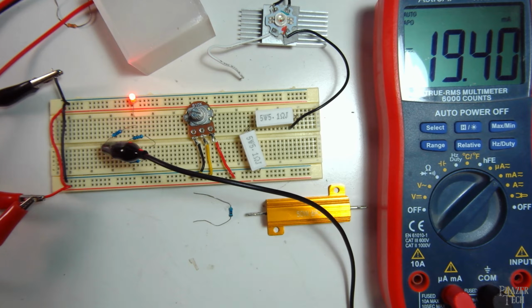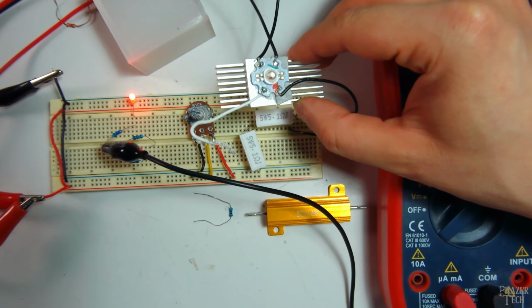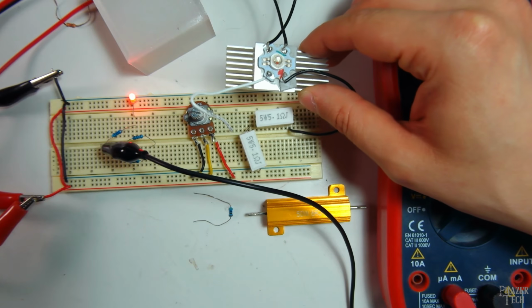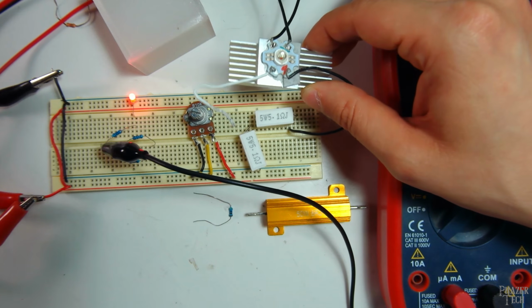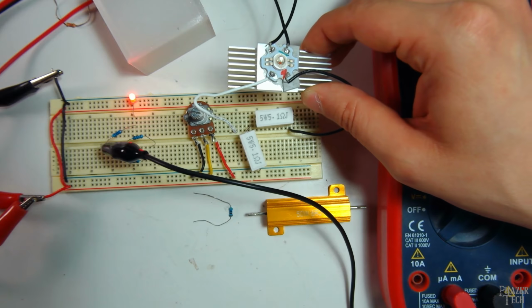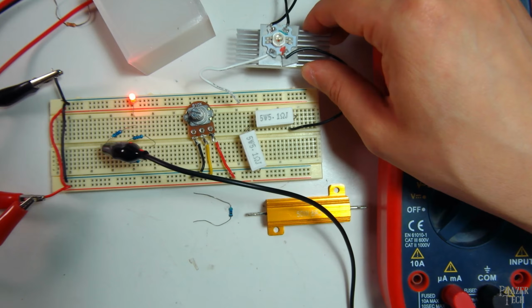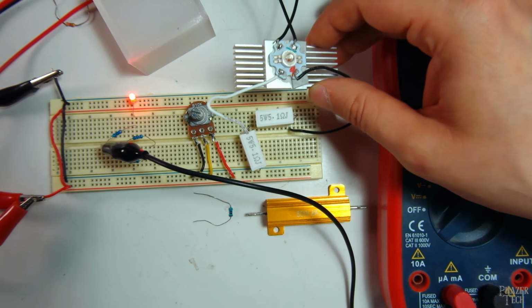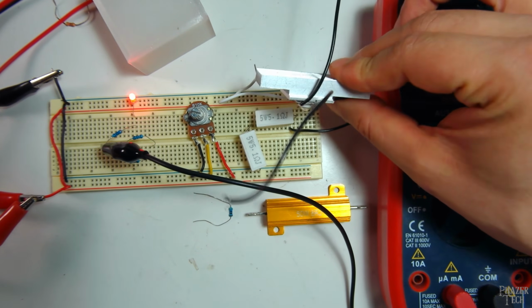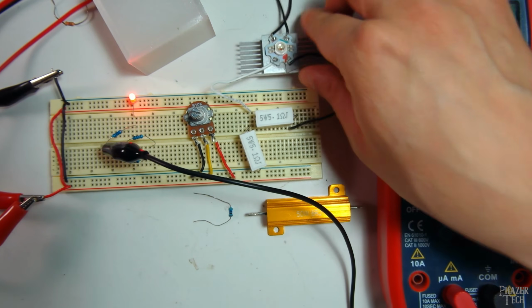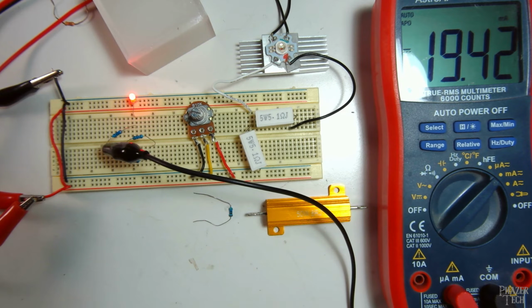But let's say we wanted to power a bigger LED. Here I have a much more powerful LED, and it's actually an RGB LED, meaning it has 3 separate LEDs. One for red, one for green, and one for blue. Each one of these is rated for up to 700 milliamps instead of just 20 milliamps like our smaller LED. It uses so much power that I had to mount it to this heatsink just to make sure it doesn't overheat. So let's say we used a quarter watt resistor to power one of these big LEDs.